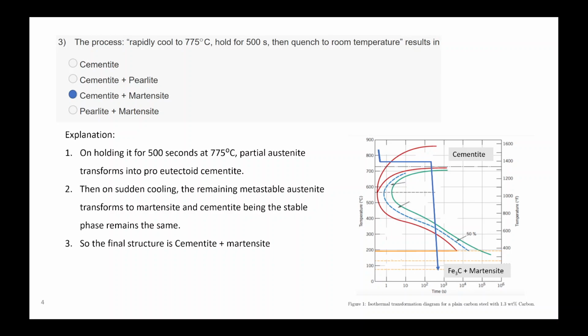If you're changing into martensite and pearlite, the main change will be in your tensile strength, yield strength, and fracture strength. Ductility will change, toughness will change, but elastic modulus pretty much remains the same. To change elastic modulus you require, for example, formation of a composite, or a change in composition. If you are changing the amount of carbon to a very large extent, or adding nickel or other constituents.